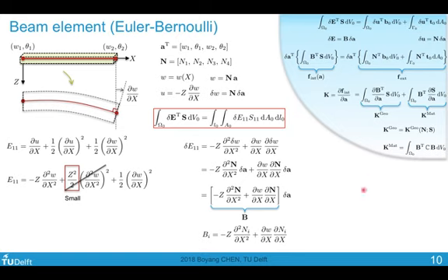To facilitate our partial derivative operation later, let us express W by its shape function multiplied with the nodal degree of freedom vector. And I again use the Einstein summation convention. So W would be Nj times Aj, where I sum over j from 1 to 4.